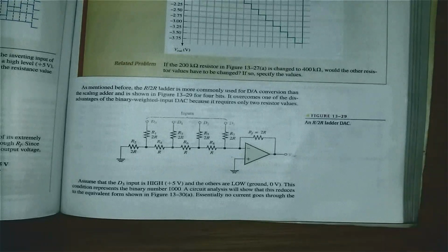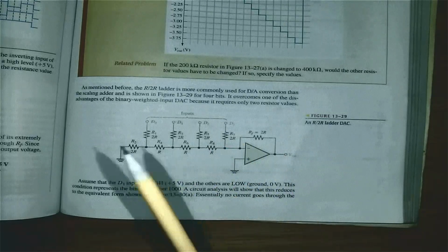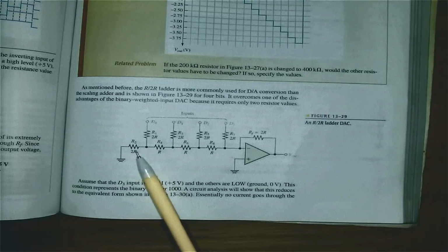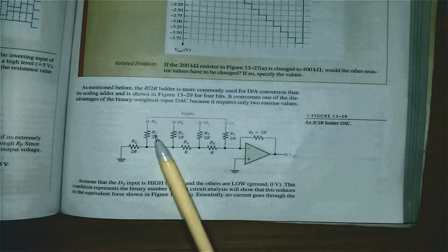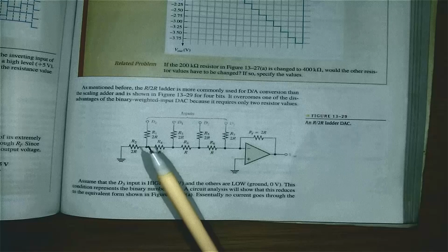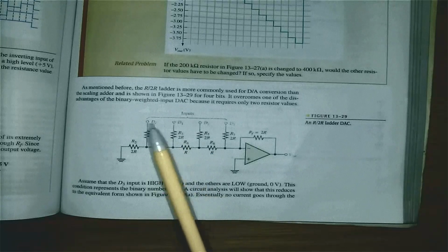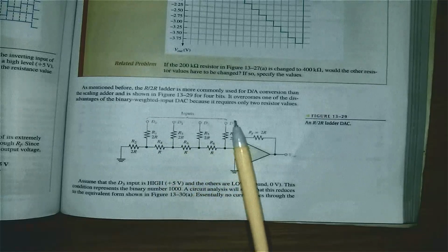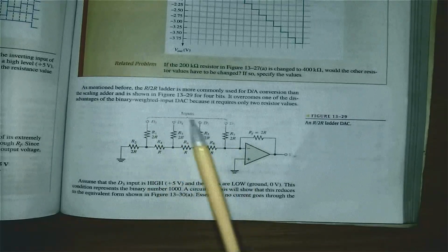The next circuit is a R2R ladder network digital to analog converter. The only thing I want you to know is the circuit diagram, and you must know which resistors are R and which resistors are 2R. That means we're only going to use 2 resistors, a 2R and an R. And very important to notice, if you have to select certain things, you can't leave these inputs open.